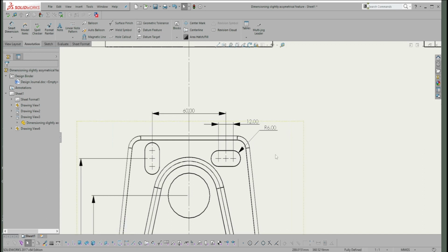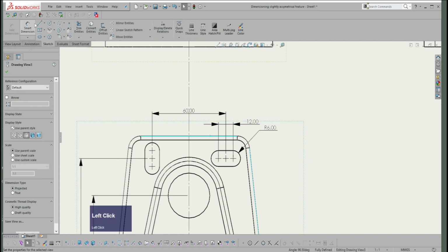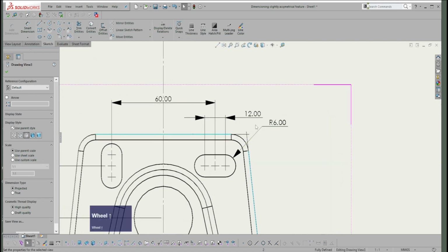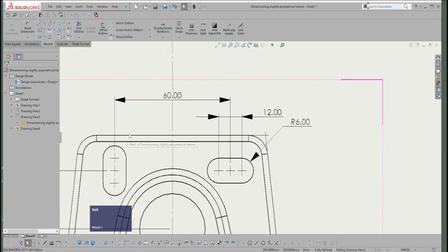In fact, the way to do it is to put in what's called a virtual sharp. So to put in a virtual sharp, you hold the shift button down, click on an edge, keep it held down, click on another edge, and then you go to the sketch environment and you select this point mark, and it'll put in a virtual sharp. So in other words, it's completing the intersection between the two lines. So I'll do that again.